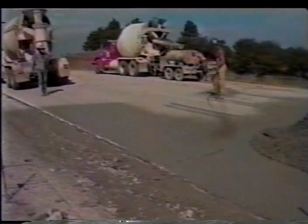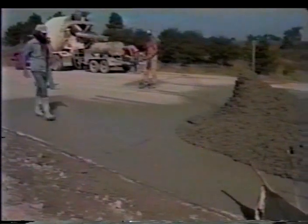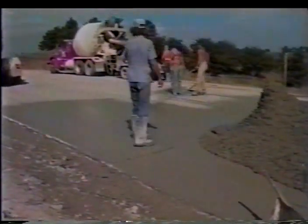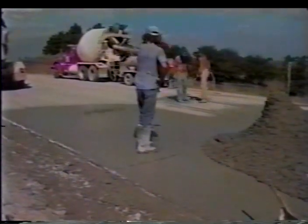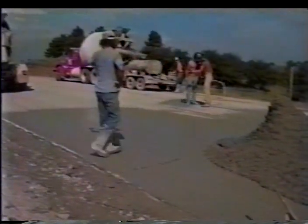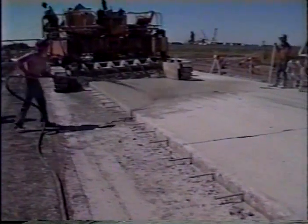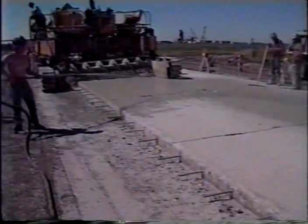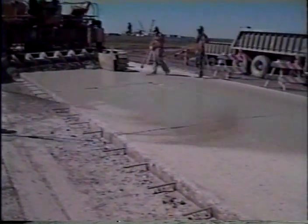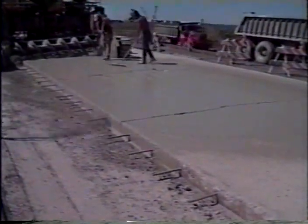As a bonding material, a neat cement grout that consists only of cement and water provides good bond strength. The water-to-cement ratio should not exceed 6/10. The grout should be stir-agitated throughout the duration of application. A mechanical spraying device is typically used to apply the grout a short distance ahead of the paver. To ensure an even coating, the grout can then be spread with either a stiff brush or broom. There should be no running or puddling.